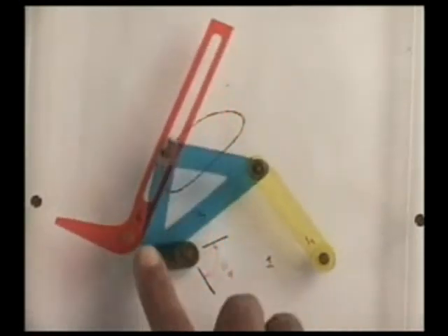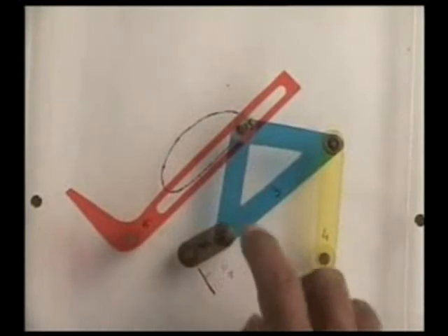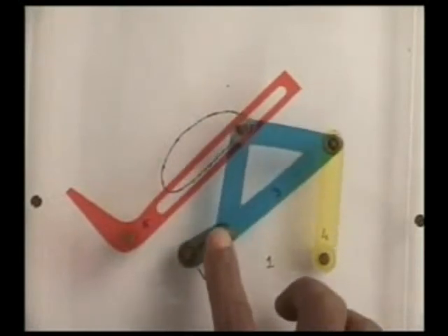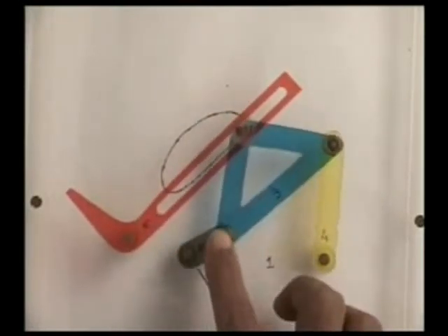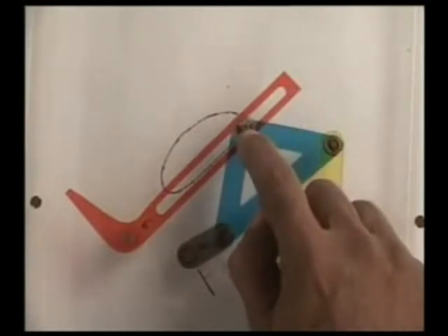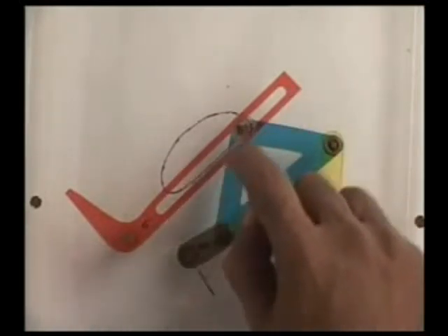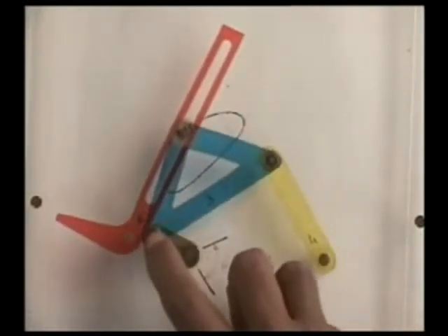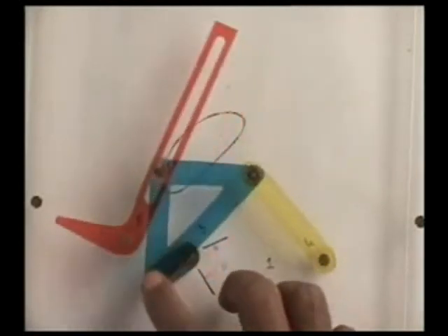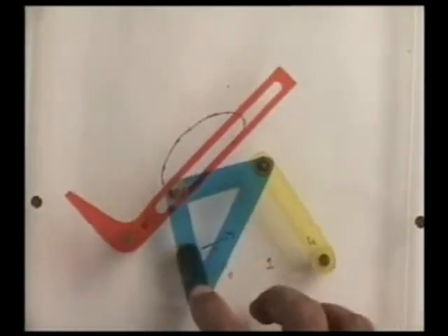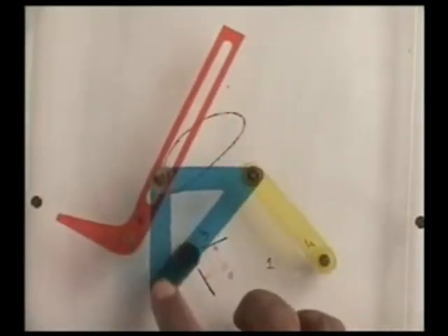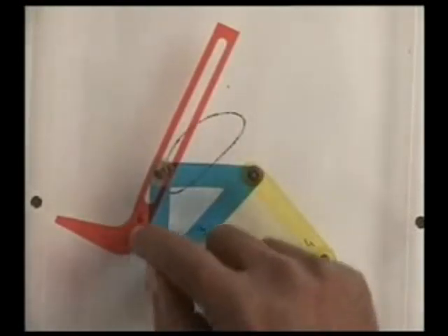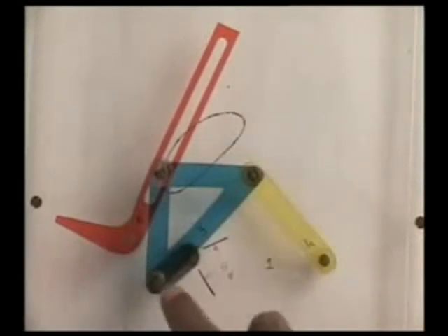As we give continuous input rotation to this crank rocker linkage, what we should notice is that during this interval of rotation of the crank, the output link hardly moves, because this coupler point goes along a fairly good approximation of a straight line. And as soon as this comes out of the straight line portion, the output link starts moving, and this is the maximum position, rather the extreme position of the output link when this line becomes tangent to this coupler curve.